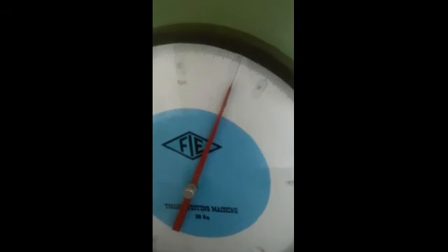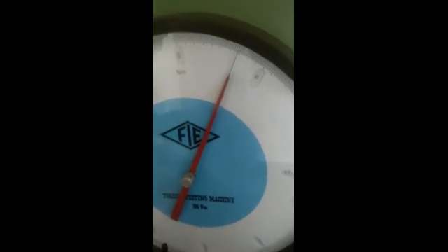First reading will be 0. Initially both readings will be 0. Then the second reading is 2 degrees, torque applied is 3.4. Next again we have to take the reading for 4 degrees. So now the reading taken is 4 degrees, and here you can see the torque. In a similar way we have to take the reading till the upper yield point.